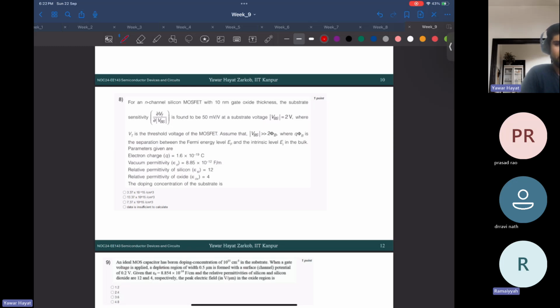You're probably talking about the ID SAT values, right? Those rise as square of VDS, true. But that is not true in general, right? I hope you know it. Partially we have linear relation. No, for short channel devices, that is not true, right? No, sir. I don't know that.